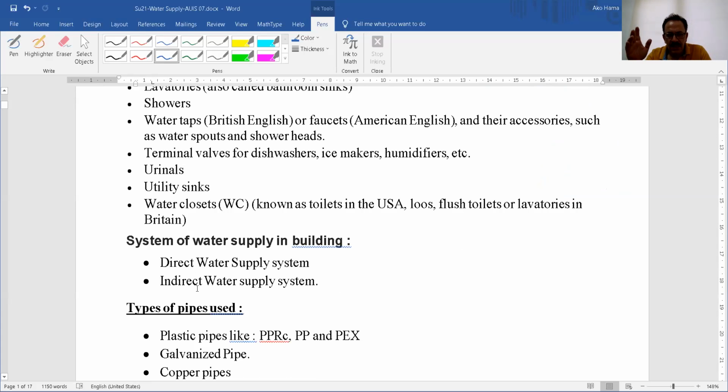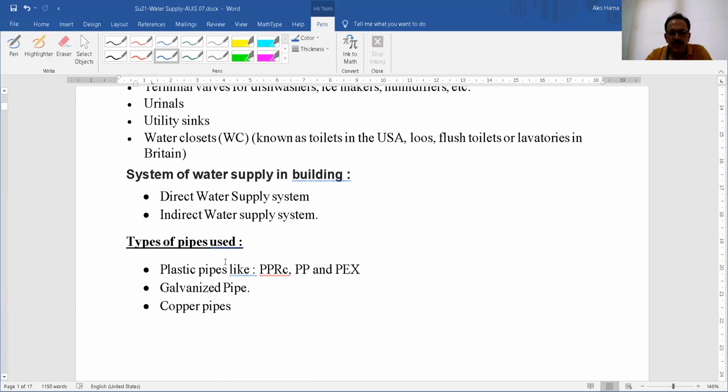We said again, we have to unify all of them together. How to do that? For each of them we have a unit, called the fixture unit, and after all, we have to add them together to find the total amount, or the load on this pipe, and see how much the total and the flow will be.